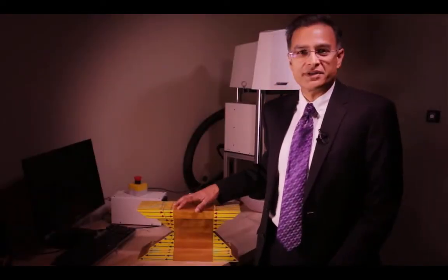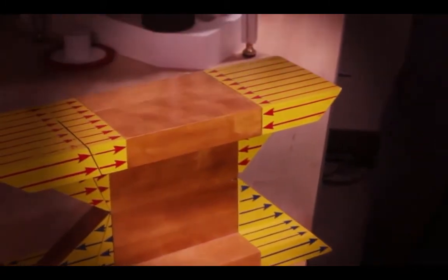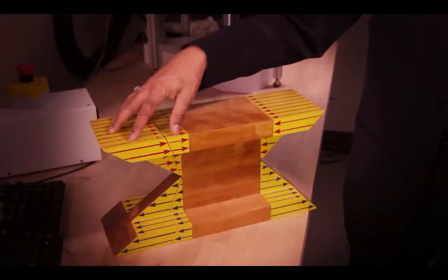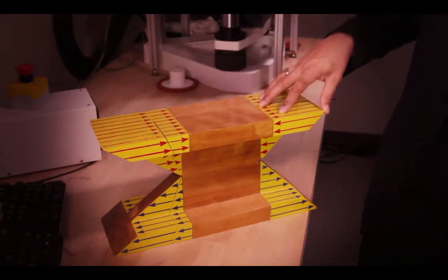So what I have here is a model of what we've just talked about, and what I've done is taken a section cut out of an I-beam, and this is delta x, and the beam is subjected to some moments and shears. And so I have a moment on one side here on this section cut, so I have the stresses from the moment on one side, and here on the other side I have the stresses from the moment on the other side.